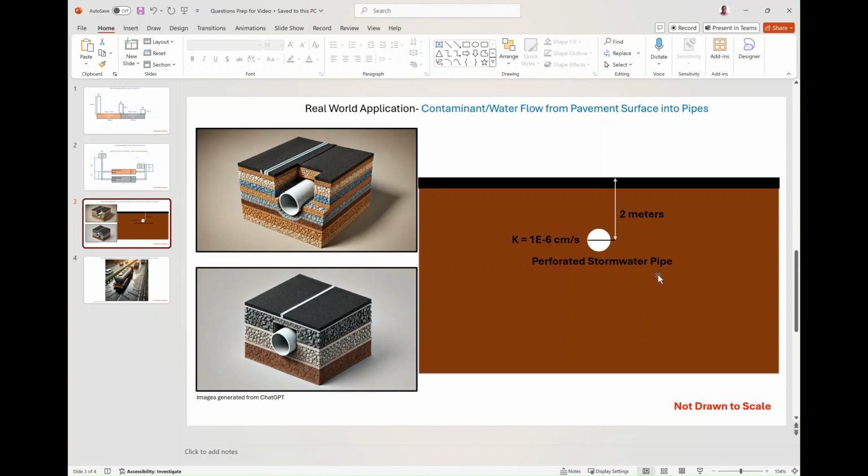There's a rule of thumb that for the lateral extent, you must do at least 2 times the vertical influence. For the vertical influence, some people might just do 3 times 2 first. That's going to be 6. So you measure 6 from this point, you are seeing my cursor, downward. So it's going to be 6 plus 2, that's 8 meters. So I might use 8 meters for the vertical extent, and 3 times 8 is 24 meters for the lateral extent to the left and to the right, making 24 plus 24, 48.